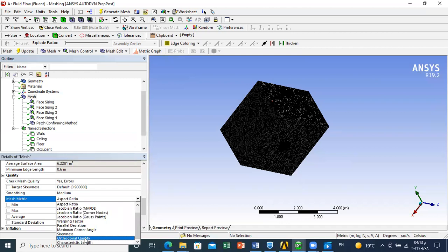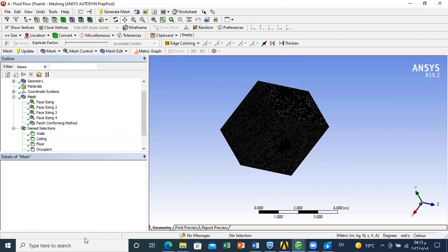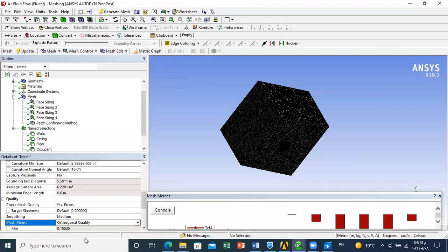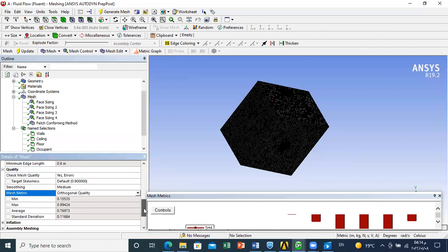For example, you can keep the method automatic, because when you keep it automatic, ANSYS will have more comfort in choosing the appropriate method. If you don't want to impose a certain type of elements, it will do the automatic way and select the corresponding type. So sometimes this might work better. Okay, so you can try several strategies.